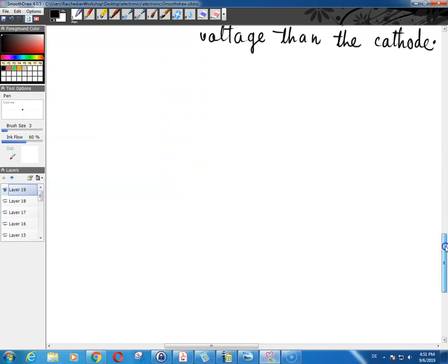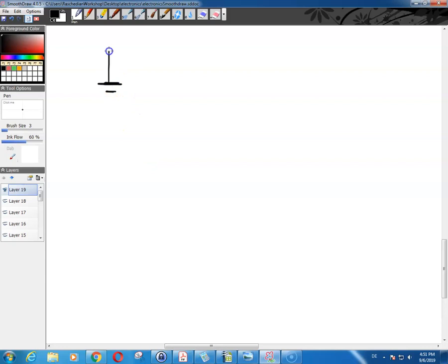And if you had some circuit like this, like the one over here, suppose that you have a resistor over here, you have some diode over here, and this diode is connected here, and if this is positive negative, you see that the cathode is connected to the positive pole of your power supply. The anode is connected to the negative pole of your power supply, and of course in this orientation your diode is not forward biased.